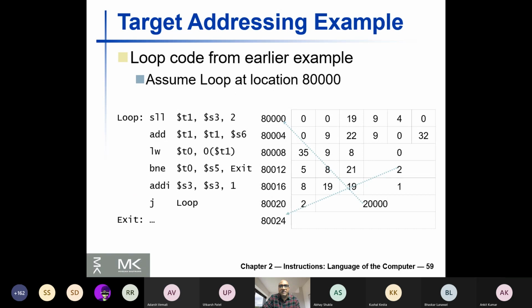And this is just a simple illustration of how these jump and conditional jump instructions work. This is the actual program we already came across in the previous class. It's just a loop statement. In the loop, you are incrementing the loop index, fetching the array elements, and comparing the array elements with some constant k. Whenever that condition holds good, we will stop. Otherwise, the loop will be iterated. So these are the set of instructions that are used.